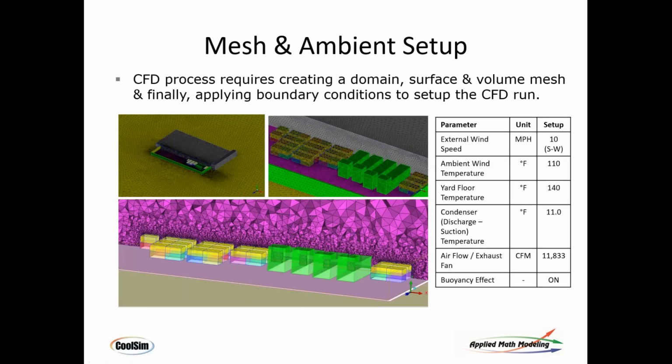The mesh is important. We need to get a good mesh here. And Abhishek, maybe you can give us a little bit of detail on the mesh. This is obviously a tetrahedral mesh that we're using here. And you can see in the image, as it gets closer to these devices, mesh density goes up. Do you want to give us a little bit of commentary about the importance of meshing and how it's done or was done in this case?